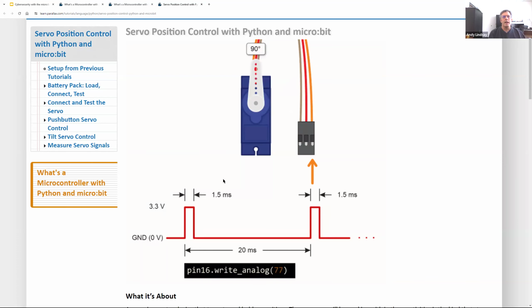And the way that angle is selected is by sending it brief high signals. If you connected a light circuit to monitor the signal that's going to this wire and ending up in the servo, what you would see, if you could, is it flashes 50 times a second.